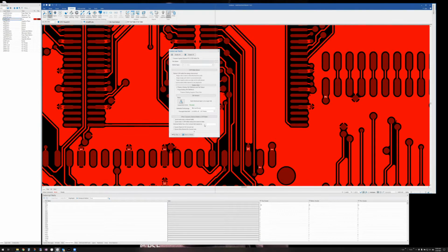Yes, we may have pads too big, spaces too small, something like that, but electrically, it matches what the designer was trying to do. To me, as a former fabricator, this is the single most important analysis I can run on a design. And it's available in the 160, it's available in the higher end, it's available for you. If you're not doing it, I imagine you are, but if you're not, I highly encourage it.